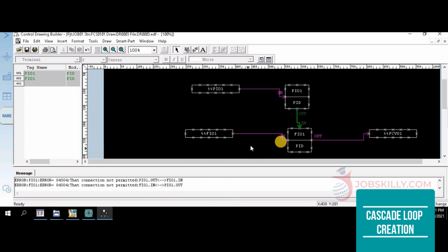See, there should be no double IN here. The 2 IN is there. This is the mistake. So just click here, and what we have to put? We have to put SET here. Okay. Go to the save option. Save it. See, there is now error 0, warning 0.